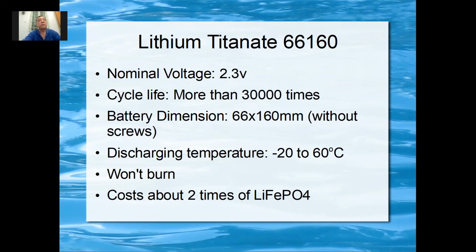Lithium titanium is normally used only in a battery pack. If you want to build a battery pack, let's say 48 volt, 24 volt, a huge battery pack, which is, let's say, 40 kg battery pack, then you can use lithium titanium. Okay, and the good thing is it has a cycle life of 30,000 times.